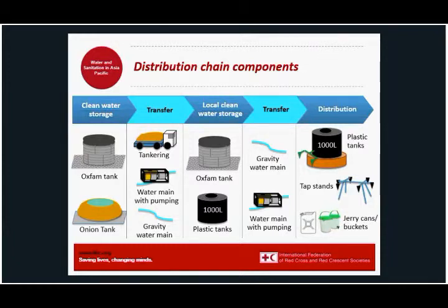For local storage, Oxfam tanks, on the left top, are an excellent medium-term option once they are established, which can take the better part of the day. Deliver water to the tap stands by gravity where available or through pumping. We also aim to provide the beneficiaries with household water storage containers. It is important to see what is available in country or what's commonly used in that area.